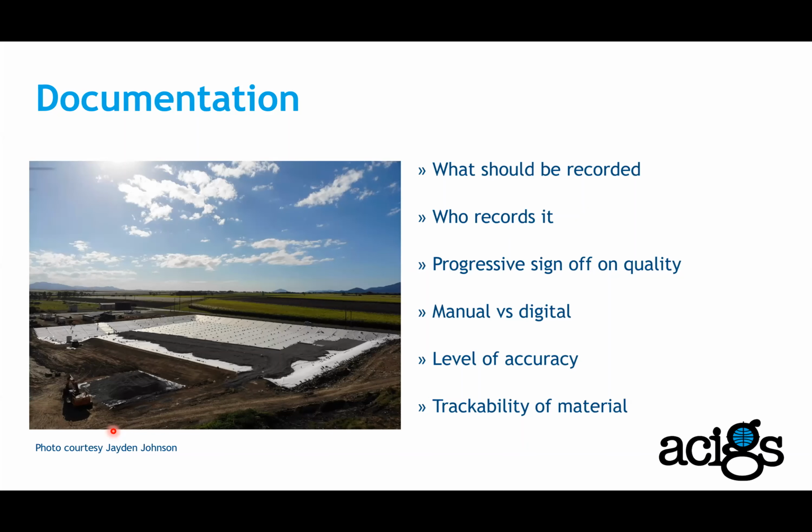Also, progressive sign-off on quality. That's an important thing because, if we see a failure in any part of the construction, there needs to be a procedure for how we go back if it's now buried under several other layers. So that is the need for progressive sign-off on the quality.